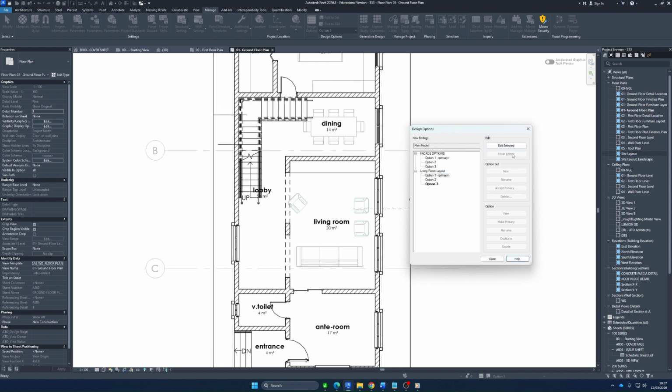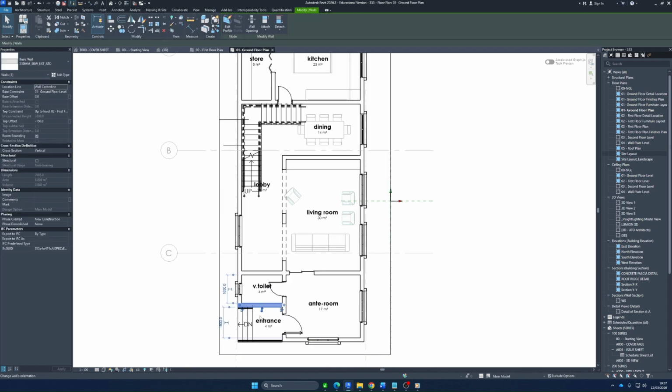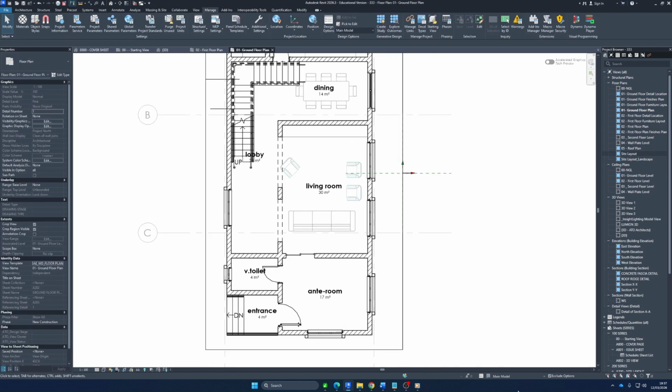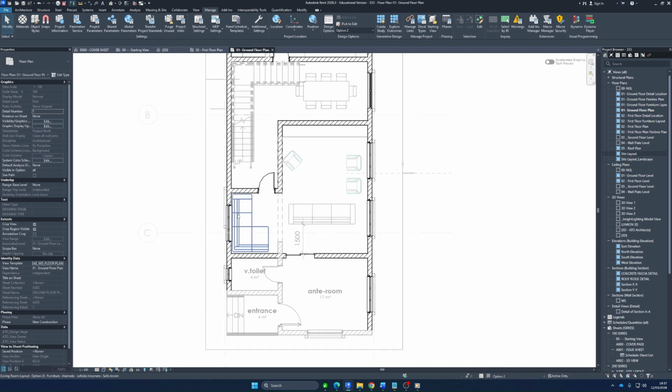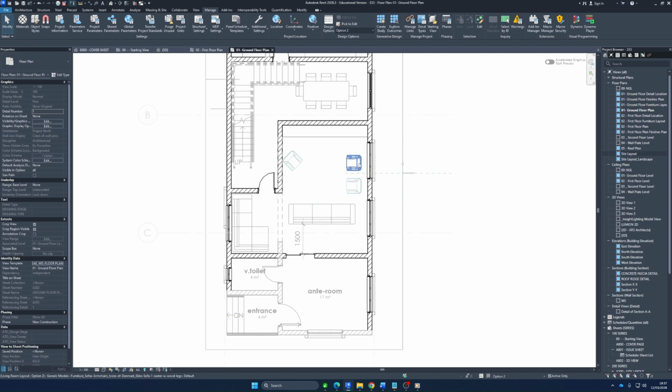Okay, so if I click finish editing here, we see that we return back to the main model mode, which is main model. We see it also here, main model. All right, and so what that primary is saying is the layout for the primary is what would show when we are in main model, where we can now select other elements that we didn't add to the design options. All right, but once we go back here and pick another option, the other elements are now selectable, and then we can see this.